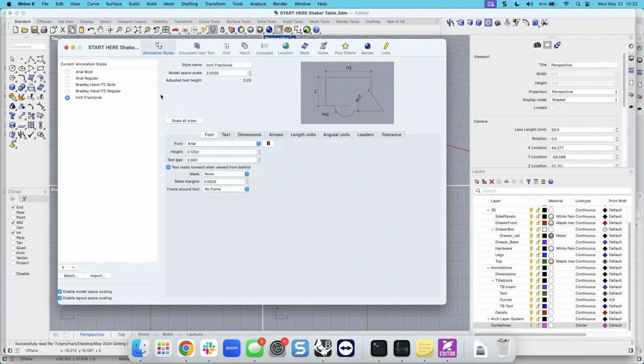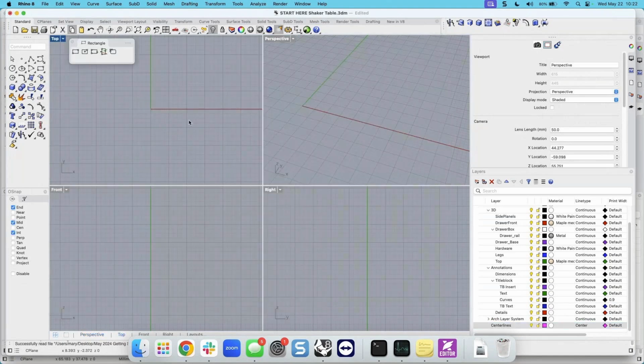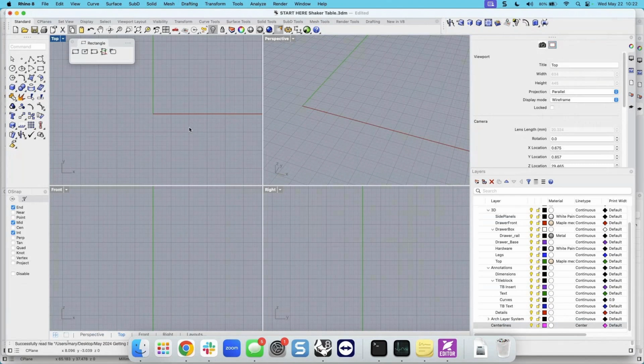Just like Eva's question, when we wanted to know how big something was, dimensions have staying power. They stay there until you delete them, so they're great. I prefer to do a dimension than do a length because length goes away. I can't see it. I forget it. So anyway, I think dimensions are fast. They're accurate with object snaps, easy to do. So I prefer to do a dimension if I'm curious how big an object is. And there will be times we'll be curious because we're making this to specific units.